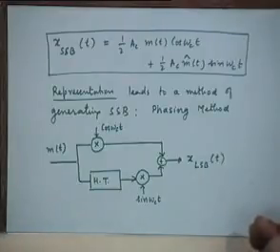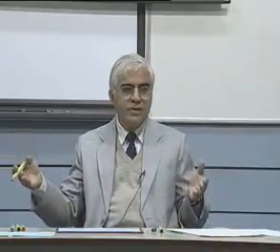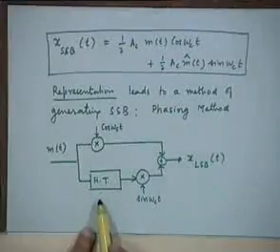So this is the second method. In the first method, you required high Q tuned filters around the carrier frequency to remove one of the sidebands, right? In this method, it looks very simple, but actually the difficulty still remains. The difficulty has been passed on from realization of a high Q band pass filter to an ideal Hilbert transformer, right?